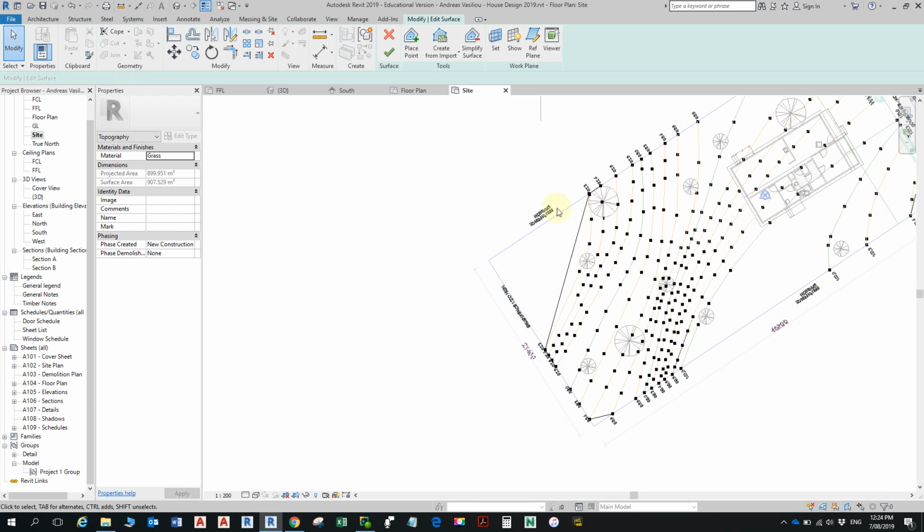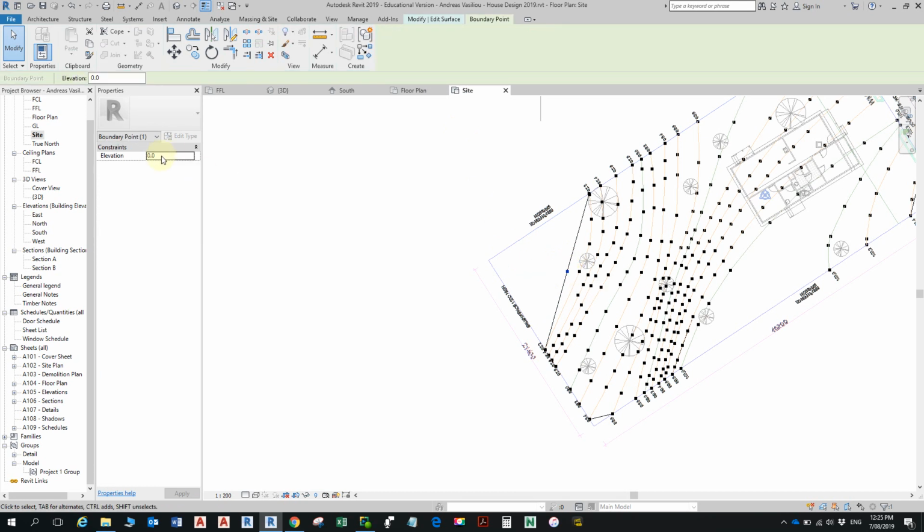All right, so what I'm going to do here is go place point. So I'm in the editing mode, so I'm going to place point, and I'm going to go here, put it in the midpoint there, just for somewhere to put it. And if I escape now and then click on that point, it says it's sitting at 0.